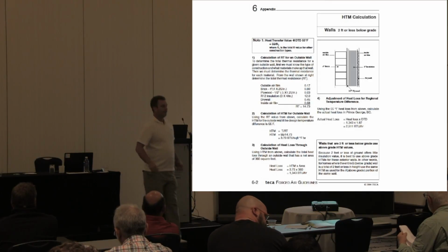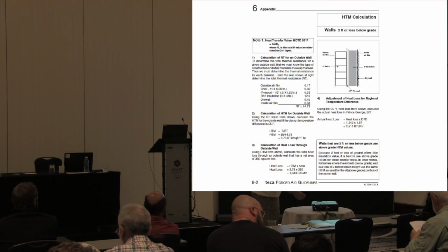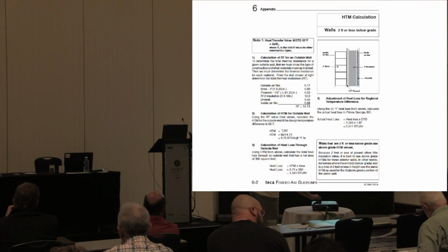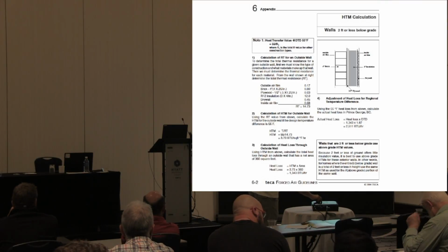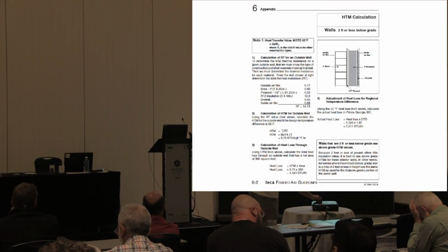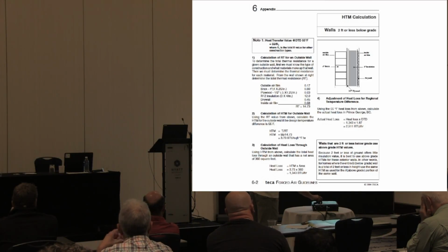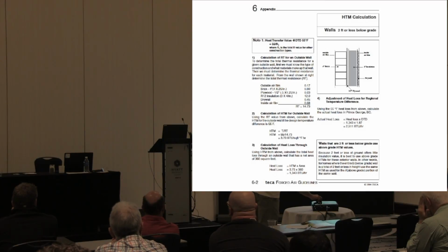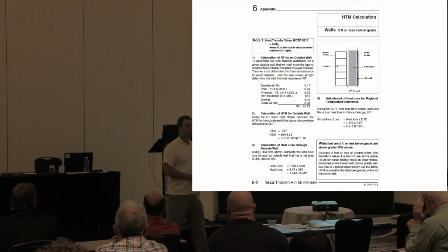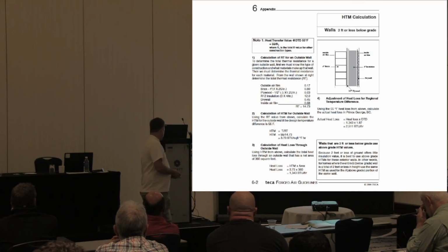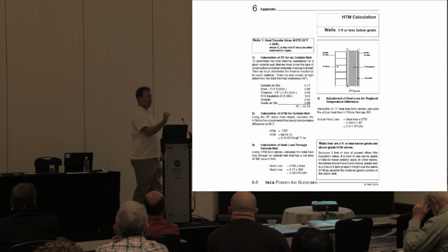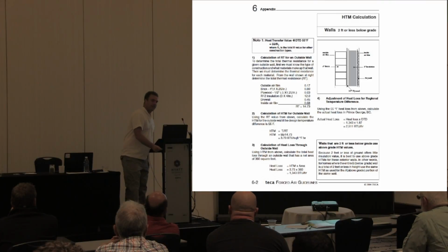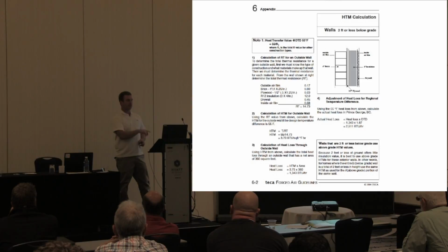In your practical experience, are you telling us before that the quality of installation of a batt definitely makes a difference in the heat loss of the building? Was that something I took out of context? Not the quality, no, just how the batt is installed, for sure. You've actually seen that happen? I've seen pictures of people's houses where it shows the batt's missing by an inch or two. Take a heat image of a guy's house, and you can tell where they screwed up the batts.